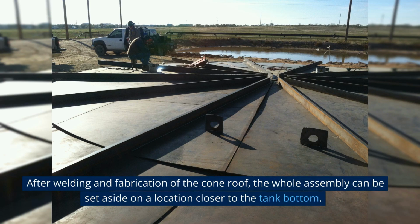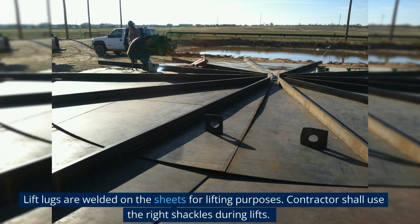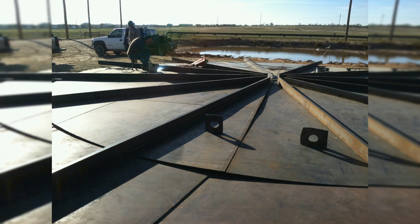After welding and fabrication of the cone roof, the whole assembly can be set aside on a location closer to the tank bottom. Lift lugs are welded on the sheets for lifting purposes. The contractor shall use the right shackles during lifts.